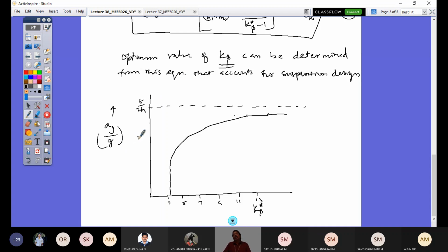In turn, that relates to roll stiffness. And to get that roll stiffness value, you should have this variation plot from this expression, and that would help you to get an optimum value of your K5. So when this is almost flat, you should take that minimum value. If I take here a value around 3, 4 K5 star, that's not the correct value, because that limits only this lateral acceleration. I have to go to this, but I should not go with the higher value.